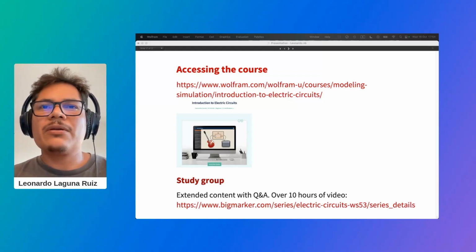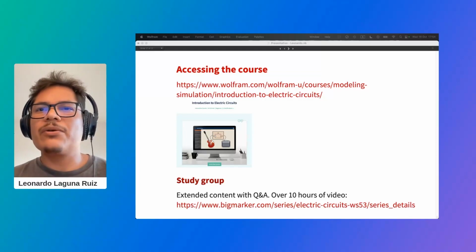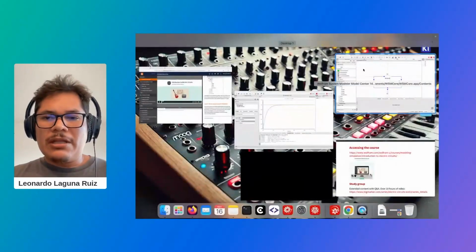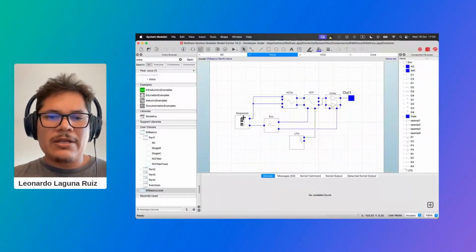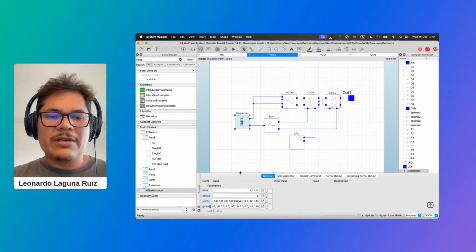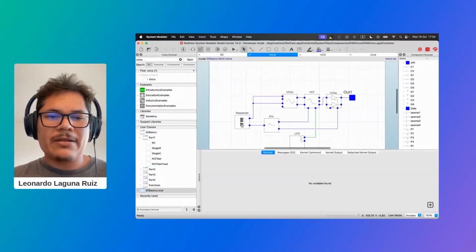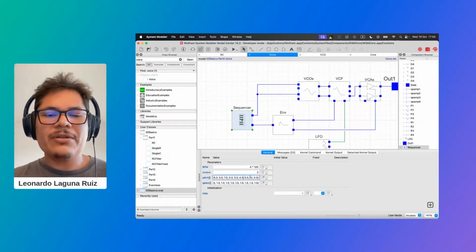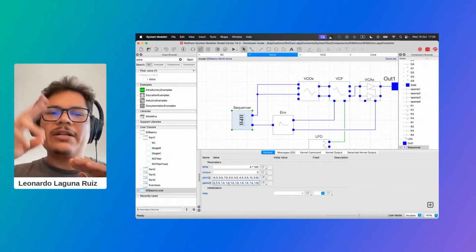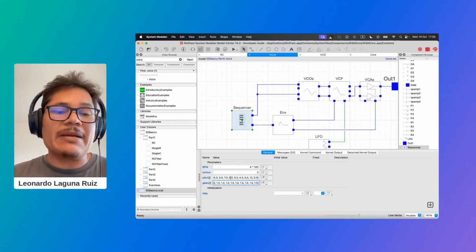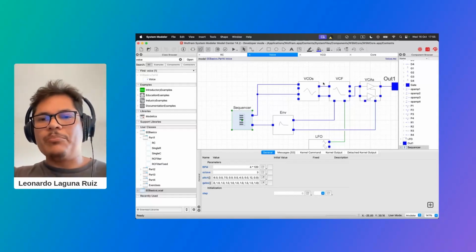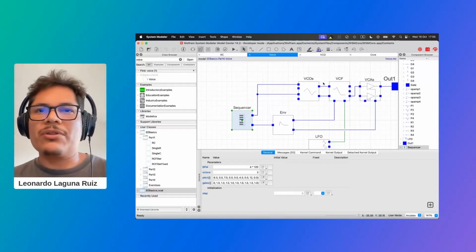So I have another question. Where is the circuitry where you are choosing the notes being played by your synthesizer? Okay, so in that case, it's not exactly a circuitry. It's a Modelica model. If you can see here, I have this sequencer object, and what I'm doing is selecting voltage values to define the notes, and gates, which is just when the note should be on or off. So this is basically my sequencer, and this one sends the voltages to the modules, which are going to produce the music.